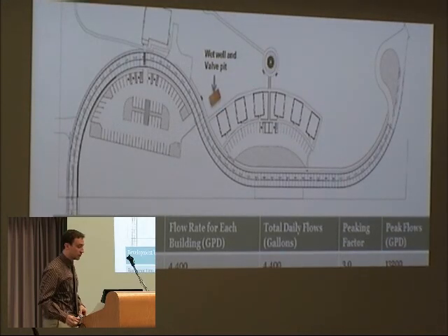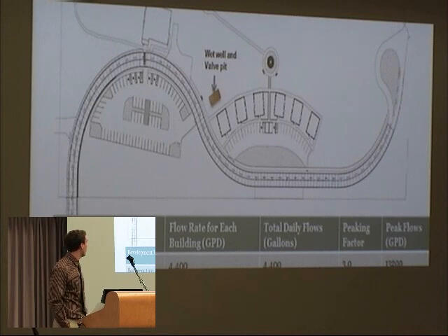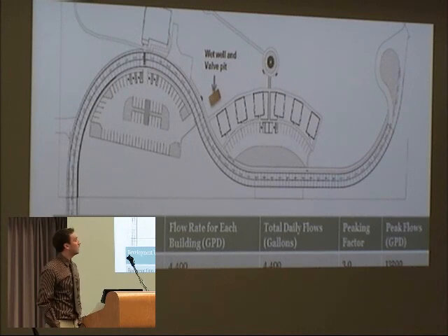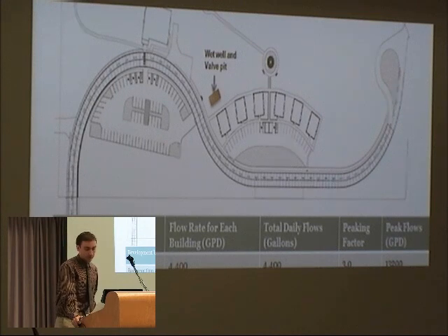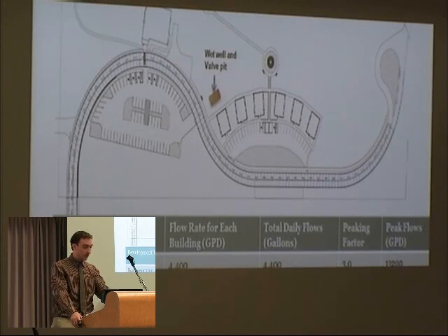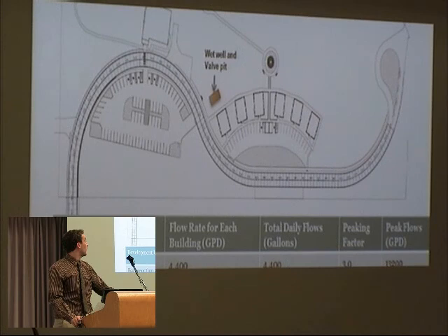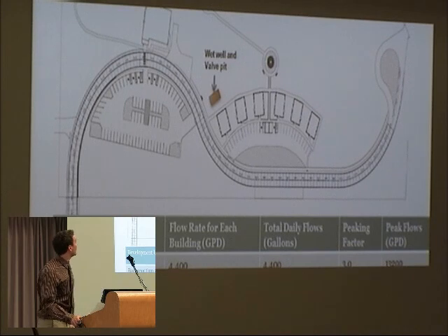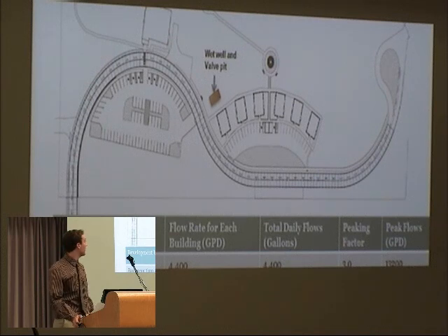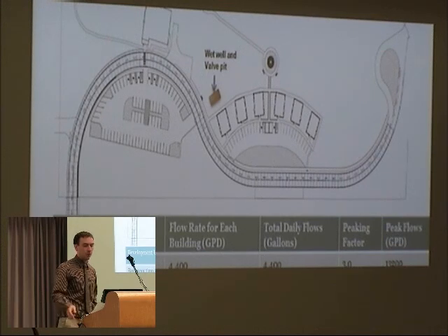In order to treat the wastewater, we had to look at how much waste we were going to produce based on the 6 buildings and the restaurant, and we concluded that it was best to pump the waste up to the main municipal sewer on Main Road, Route 138.